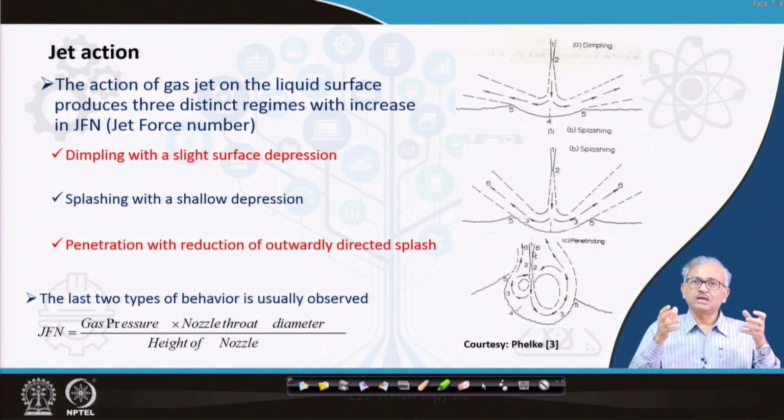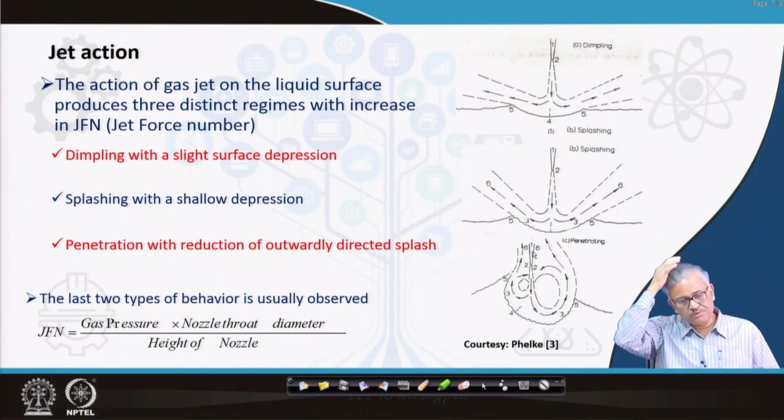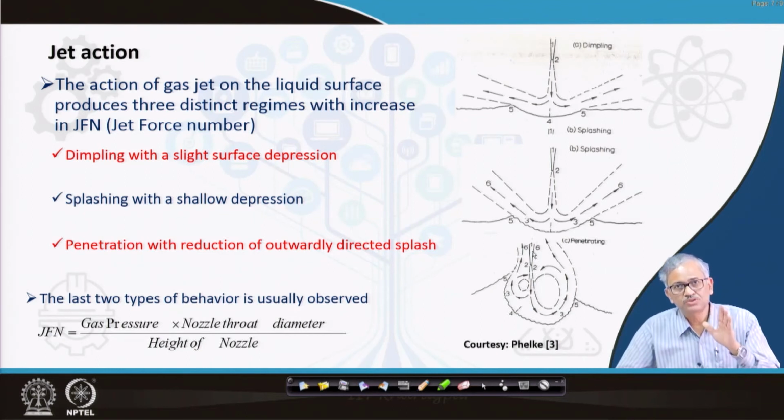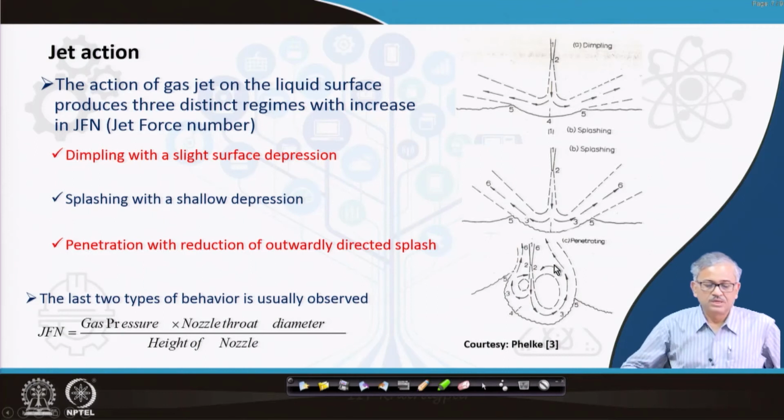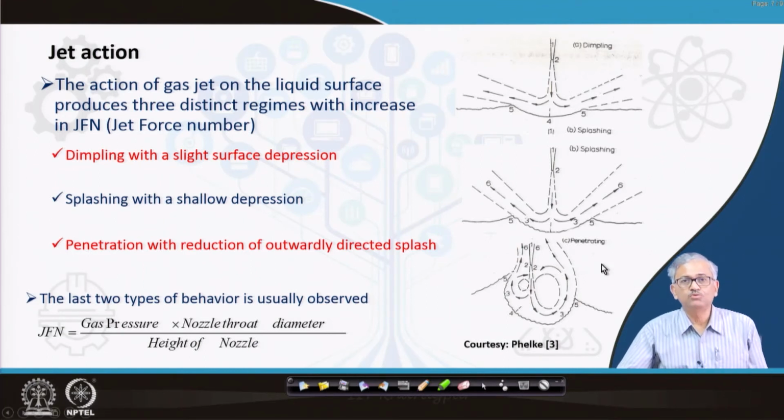And also the CaO does not dissolve immediately, some temperature is required. So after some time, when the temperature is high and FeO is significant, CaO easily dissolves, makes the basic slag, and then the phosphorus removal starts. Anyway, all these things I will discuss. So soft blowing is good for treating a very high phosphorus steel sometimes, because initially you need to build up the FeO in the slag. Okay, that is called the soft blow.